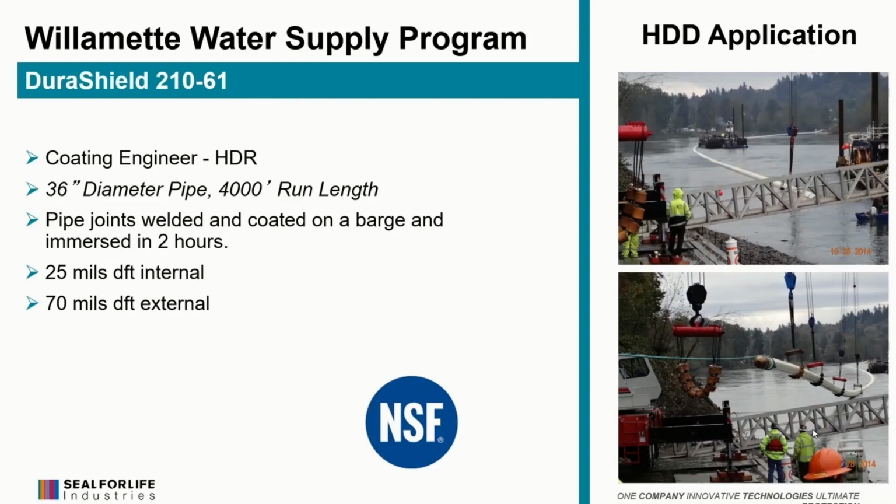It will take a 3/4 inch mandrel bend test and pass at 70, 80 mils. That's just taking a piece of steel and bending it around a 3/4 inch mandrel. Now you check for holidays, cracks, and anything in the coating surface, and it passes those tests at that thickness. So that's one of the bonuses for HDD. You don't need to put a second coat of something on there for sacrificial protection.